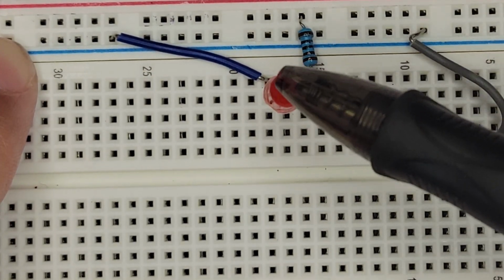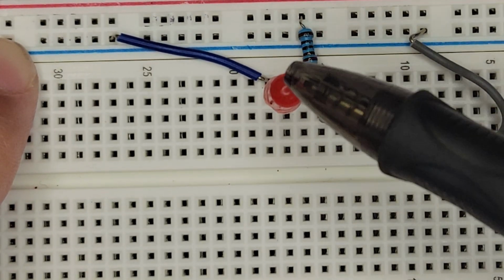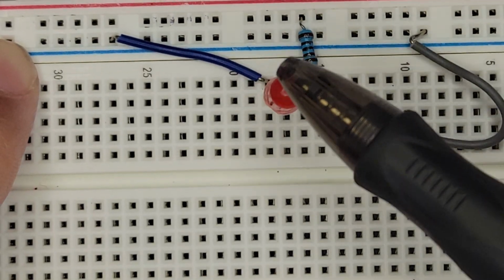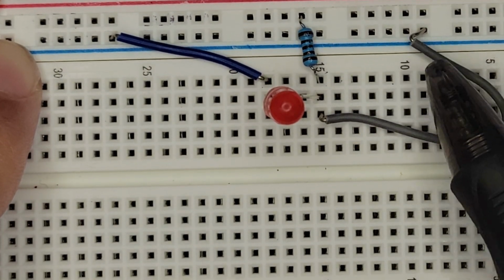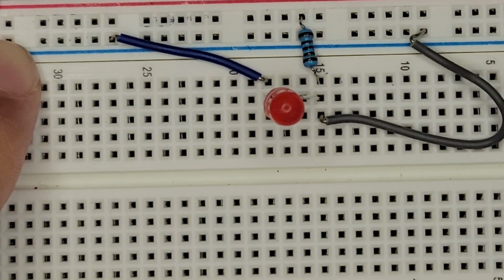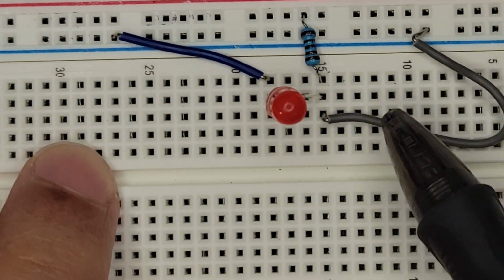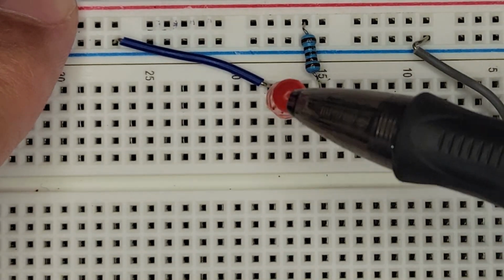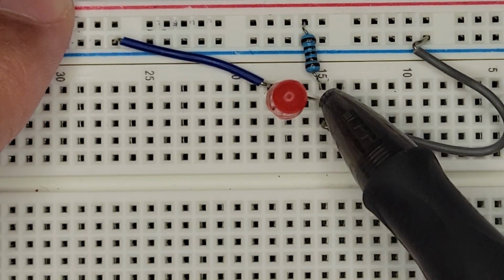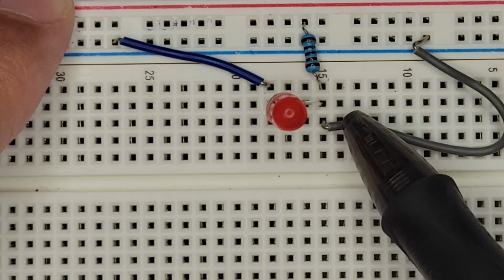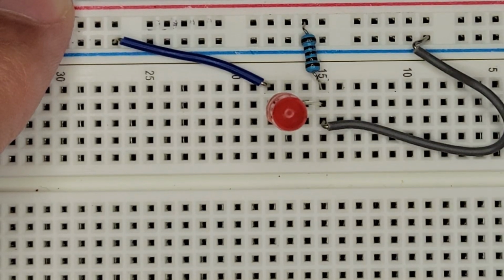One of them is pretty high in resistance. As we saw earlier, it dropped our current from 3.3 milliamps down to like 1.5 milliamps. So this guy has a lot of resistance. And this wire itself has nearly no resistance. So we can take some readings and kind of figure out what's happening. But basically, since there's resistance this way, as soon as we connect this other path, all the current drops out of the LED and takes its way home. So by using resistance, we can choose which way the electricity goes.